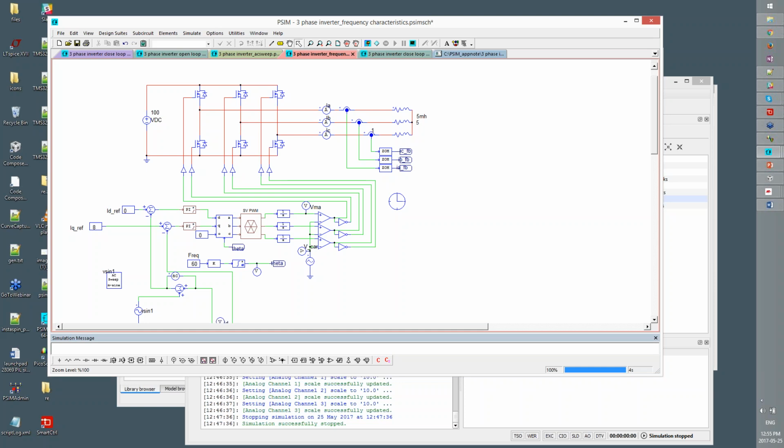The nice thing with the Typhoon HIL setup is it has this interface card for the TI MCUs already defined. So all we need to do is take the MCU that we want to use, download the code to it, and run it against the hardware-in-the-loop setup. I don't know what dSPACE has in that regard.